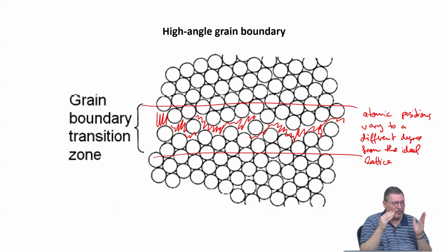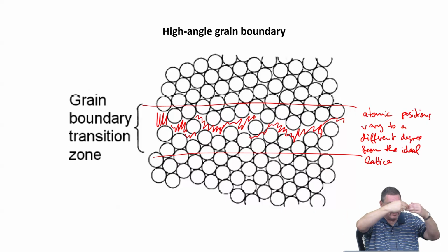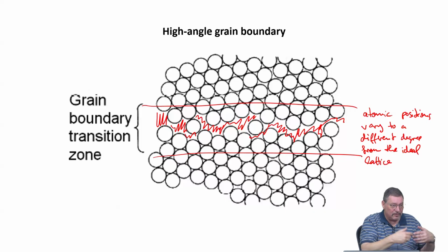What happens to the dislocation once it's in the boundary, in a high angle grain boundary? It dissociates, it loses its character. It can become a secondary grain boundary dislocation, but then the Burgers vector of that secondary grain boundary dislocation is different from the original Burgers vector, which is defined by the crystal lattice it was coming from. So it means dislocations, once they went into the gap, into the sink, are no longer the same dislocation. They split up, they dissociate, they become something different.